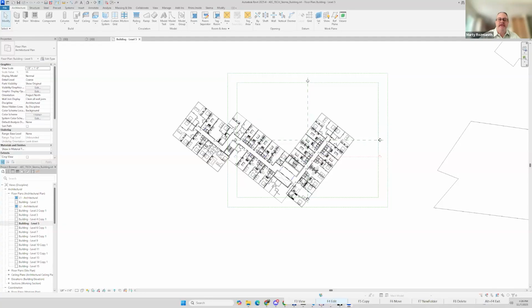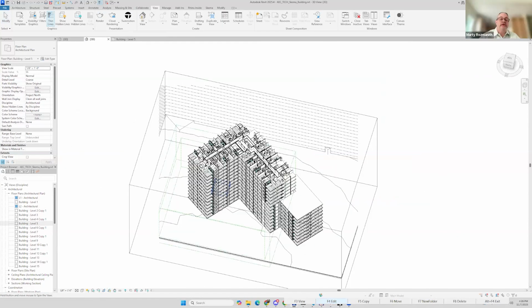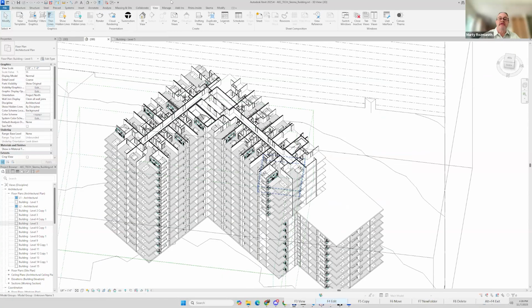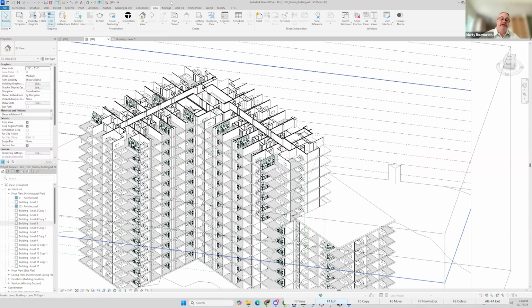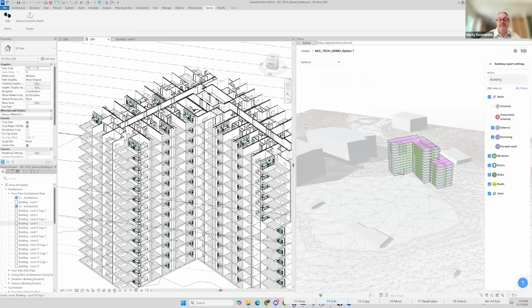One of the things about the pre-release Revit plugin, while he's working on that, you should understand is if you've used our stuff before, it was pretty much one and done. You didn't have very much control over what came into Revit from Schema. We just sort of dumped everything in there. The new version of the Revit plugin is different in that you can control which pieces and parts of the schema generated building go into Revit. In this case, we've stripped out the exterior facade because we're going to do a custom one using Grasshopper.